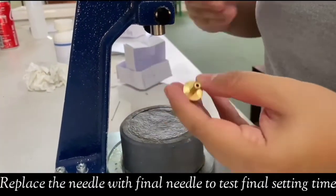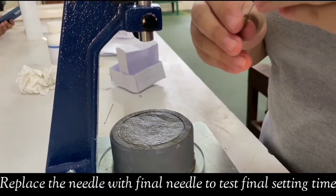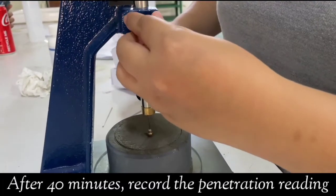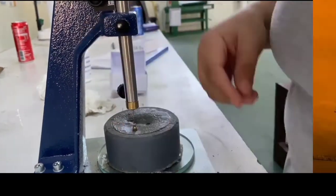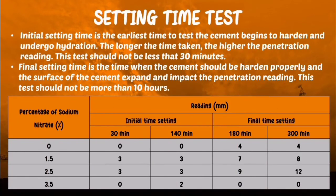After we have done with the initial setting time, replace the needle with the final needle with an annular attachment to test the final setting time. After waiting for 40 minutes, release the plunger and record the penetration reading. Repeat all the procedures for each sample that was added with sodium nitrate at different percentages, which are 1.5%, 2.5% and 3.5%. From this table, we can conclude that the cement hardened quickly when 2.5% is added to the cement mixture.